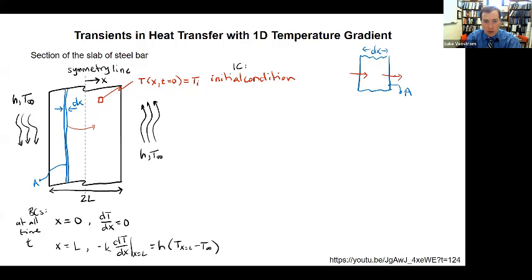Then the heat transfers from left to right. So I have some conduction that goes in on the left face, and I have some conduction that comes out on the right face. And I have now also some storage on the inside because this thing is not steady state anymore. I apply the same heat transfer energy balance equation, right? So we have E dot stored is equal to E dot in minus E dot out plus E dot gen, right? There is no generation, right?